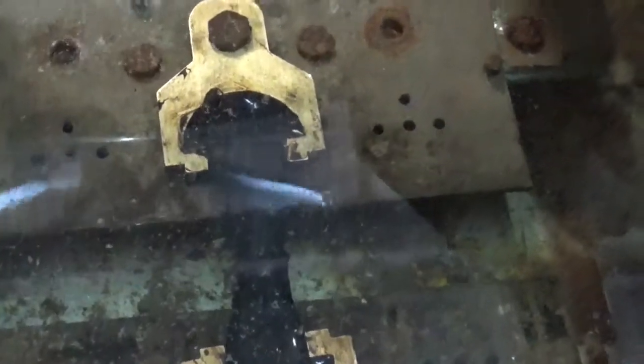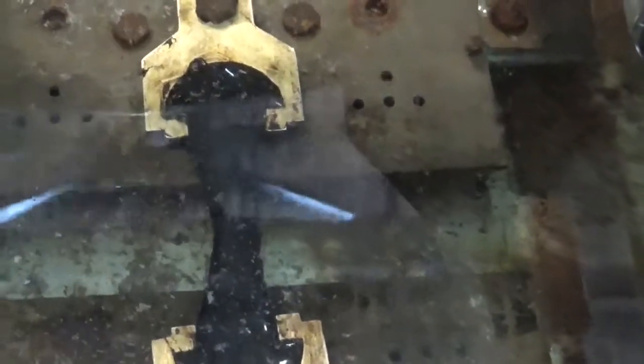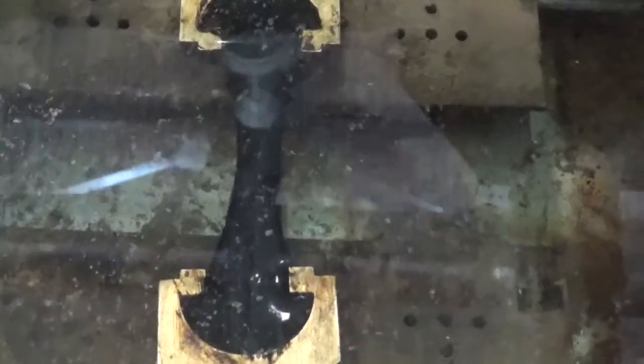Slowly this is getting stretched and it will get converted into a small wire. Let us see how much it can stretch. The break point, the point at which this fine wire of bitumen breaks, that point we can see as the ductility.